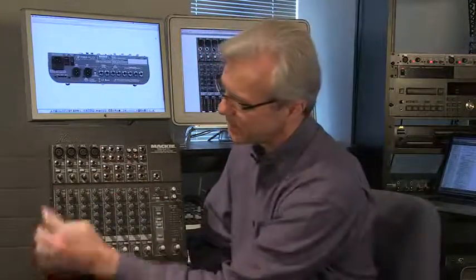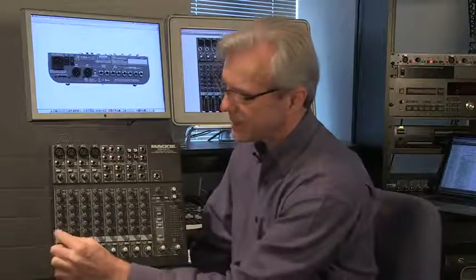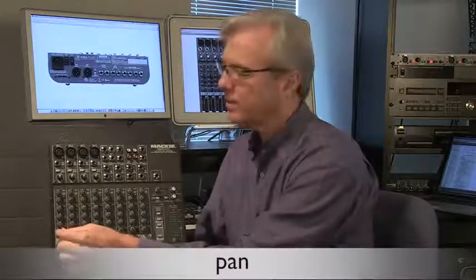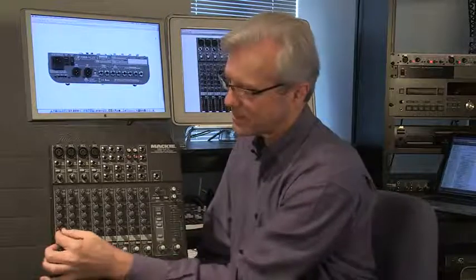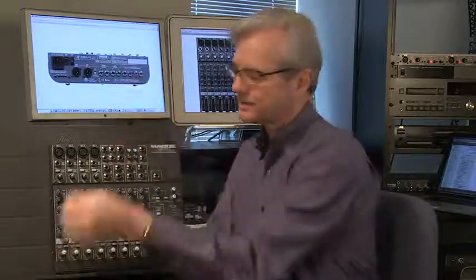The next knob coming down, I'm going to come back to these in a second. The next knob is what's called pan. Remember, this is a stereo output, so we can go left or right. If this microphone coming in, I want to send it to the left channel, then I take my pan knob, move it to the left, and then it would only come out the left channel. If I move it to the right, then it only comes out the right.